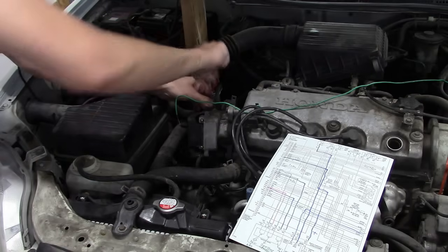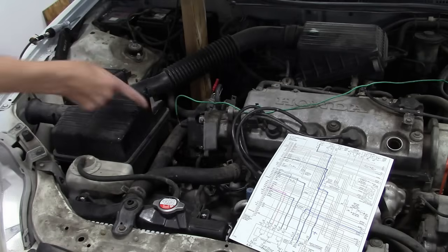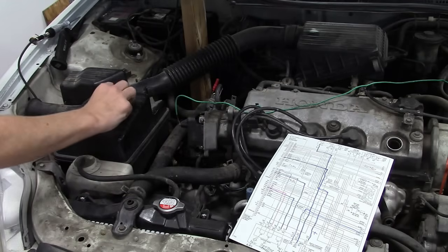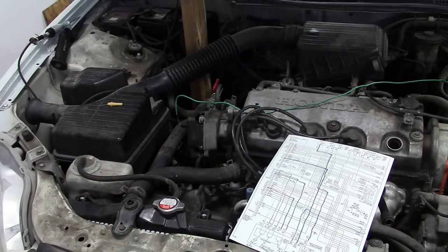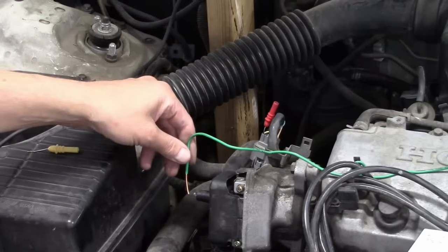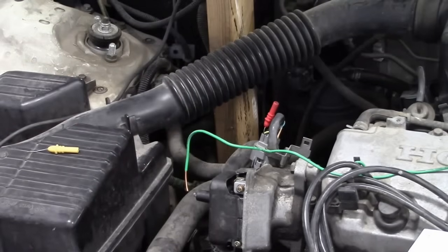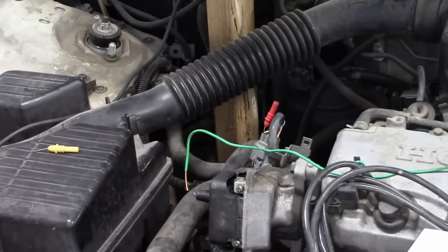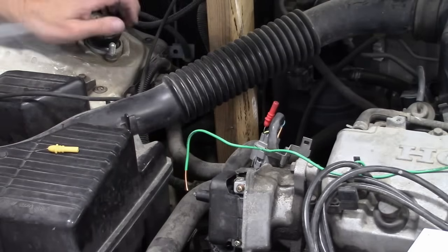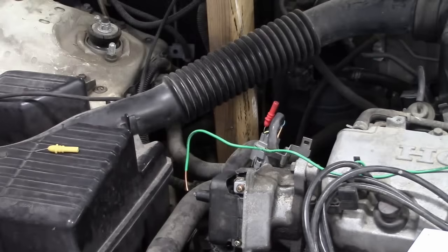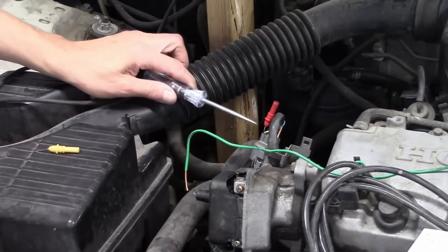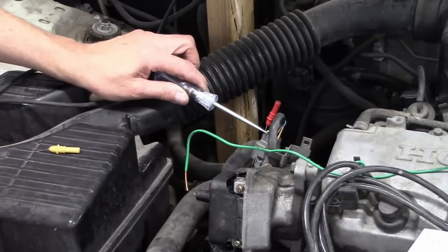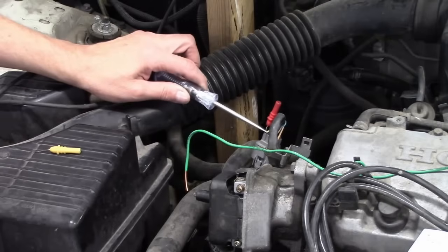Should be able to create an ignition signal and create a spark. So the first thing I need to do is make sure the ignition is on. All right, we'll adjust my spark gap so you can see that, and we'll see if a spark jumps there. And what I want to do is get my test light to battery positive. And I just verified we've got ground there. So I want to put a little signal in here, just low voltage, and wow, nothing happens.